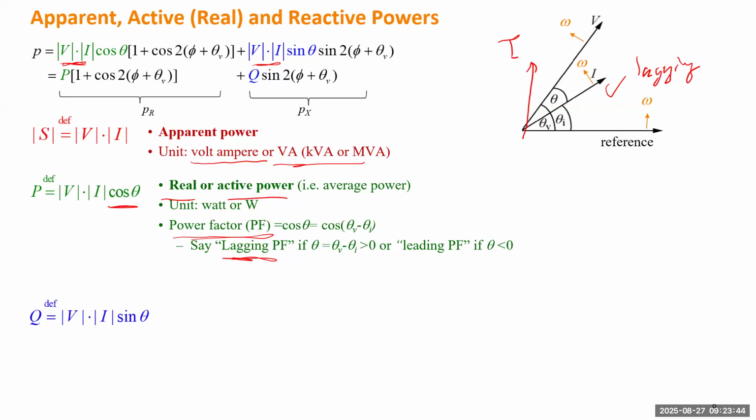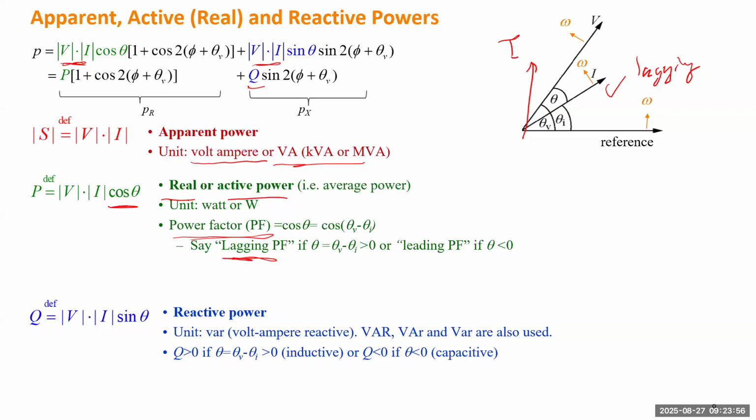Okay, for the number at the beginning of the second item, we call it Q. That's apparent power multiplied by sine theta. So this one is called the reactive power. This is the number of 3,464. That indicates how much the load can exchange energy with the source. But that doesn't cause any actual energy loss or consumption.